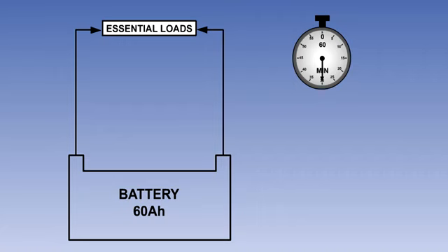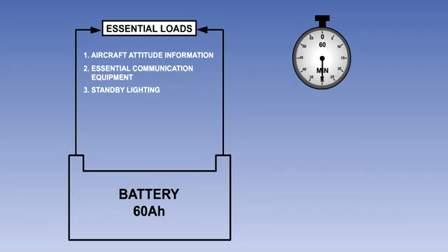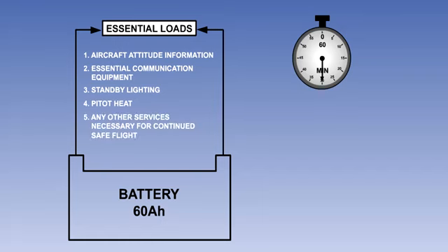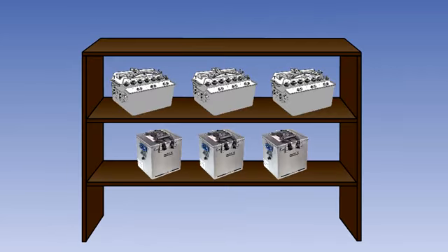Essential loads will include aircraft attitude information, essential communication equipment, standby lighting, pitot heat, plus any other services necessary for continued safe flight. Spare batteries will be held ready for use in the electrical workshop.